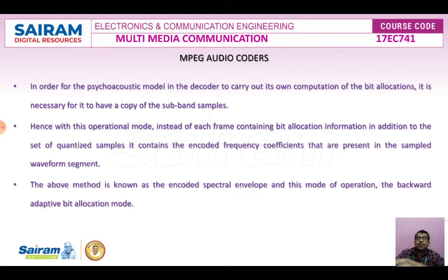This approach is used in a standard known as Dolby AC1, where AC indicates acoustic coder. Dolby AC1 was designed for use in satellites to relay FM radio programs and the sound associated with television programs. It uses a low complexity psychoacoustic model with 40 subbands at a sampling rate of 32 ksps, proportionate to 44.1 and 48 kilo samples per second.